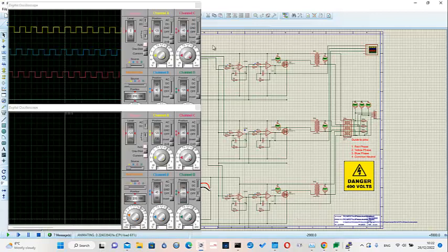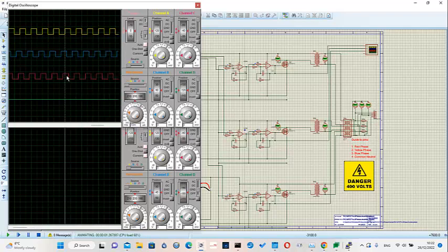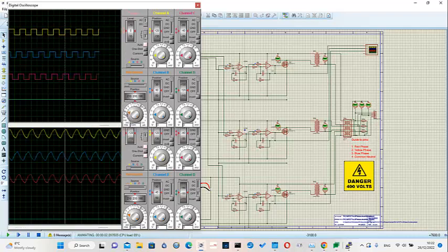It'll take a moment, but straight away you can see that the microcontroller is outputting our square wave at exactly 50 cycles per second, with a time period of 20 milliseconds. The time base is set to 10 milliseconds, and it takes 2 divisions, 20 milliseconds, to complete a cycle, which is exactly what you would expect.